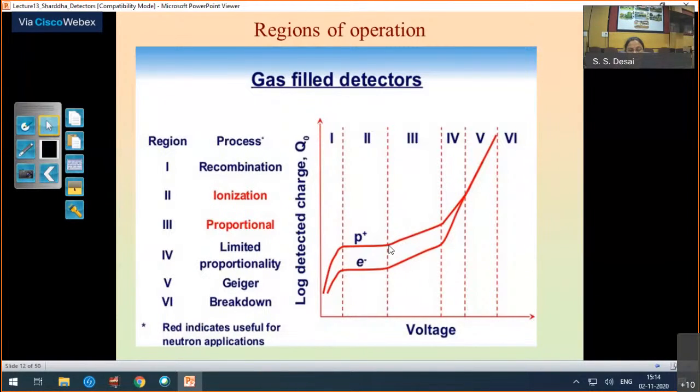When voltage is increased beyond a certain stage, we reach the avalanche formation. The electric field between the electrodes is so high that the electrons are accelerated to form secondary electrons, and this avalanche continues till the anode is reached. That is why the number of electron-hole pairs gets multiplied by a specific number, called the amplification factor of the detector. By amplifying this charge, we get a signal much beyond the noise, and the amplification reduces the constraints on external electronics to see the signal pulse.